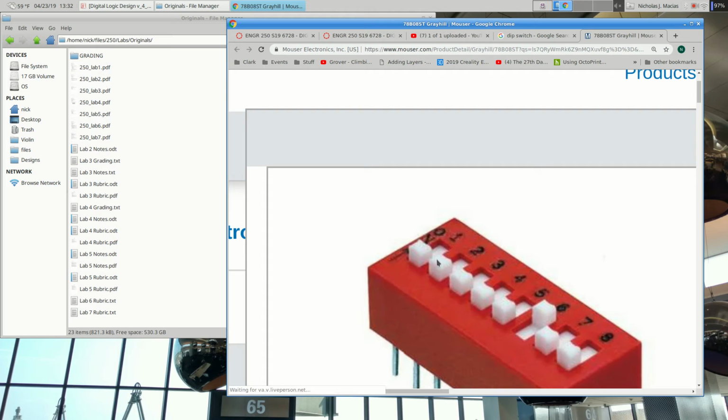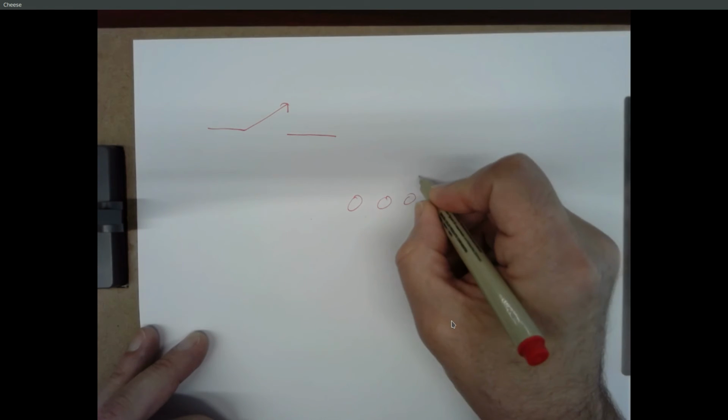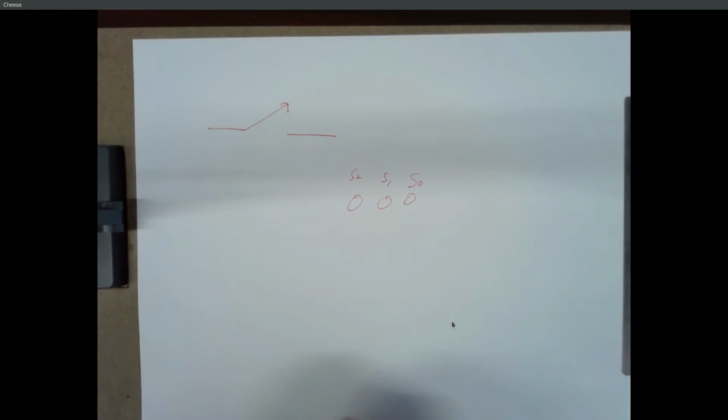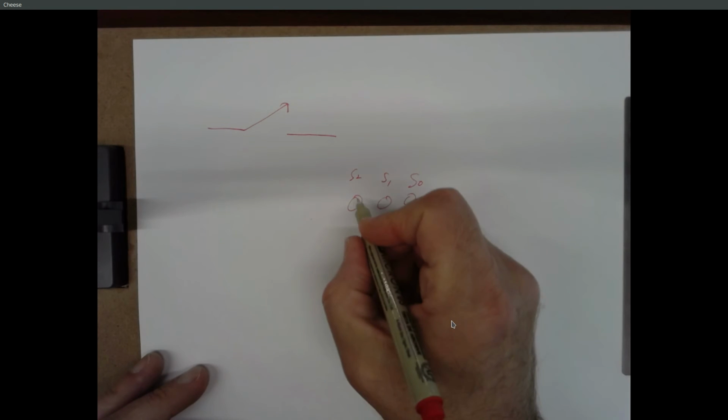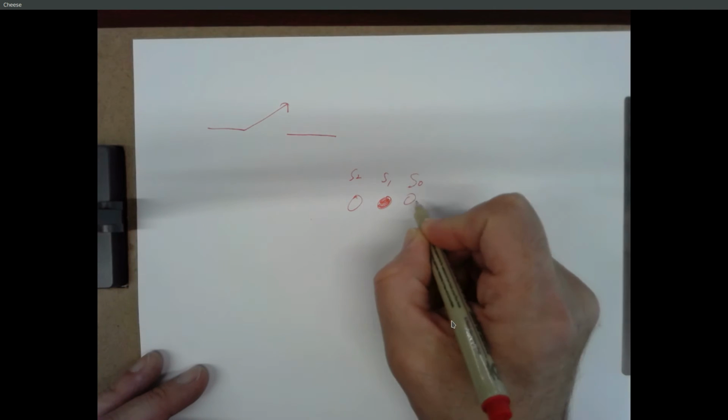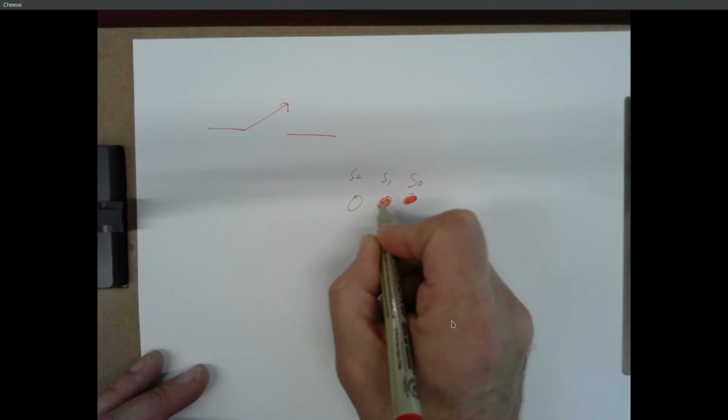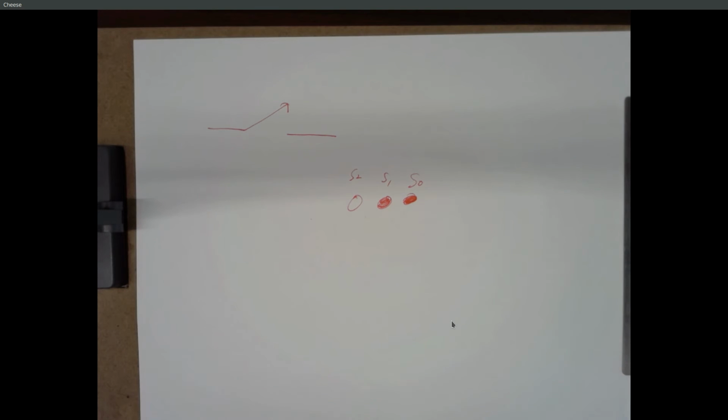Right now, those switches are down, those switches are down. It's doing 0 plus 0. It should give an output of 0. Well, how do we display an output? We could have 3 LEDs, and this could be bit 0, 1, and 2 of our sum. So if the sum is supposed to be equal to 3, you'd expect this LED to be off and these 2 LEDs to be on. And you'd say 011, that's a 3. So you're going to put 3 LEDs into the output of your circuit to make sure that it's adding correctly. But we're going to do something even cooler after that.